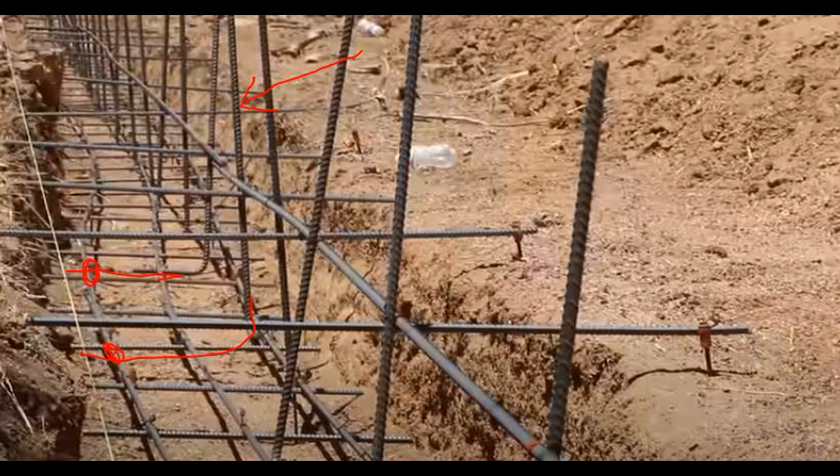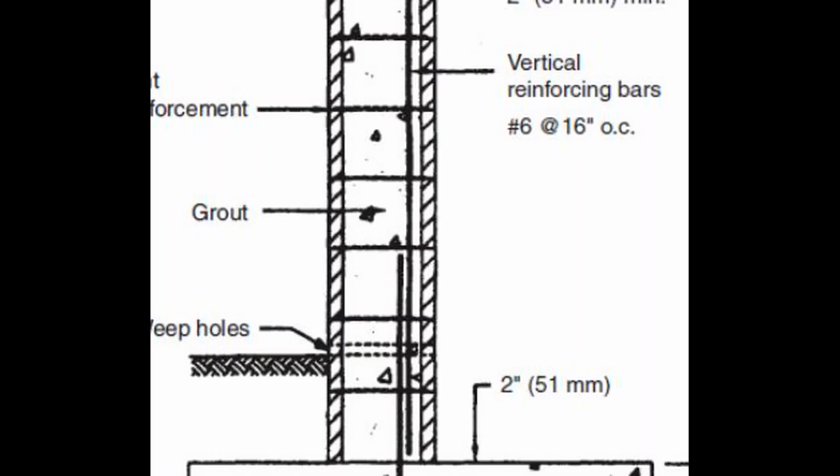So ideally, if they are subject to lateral pressure, which can be from soil, clay, or maybe lateral pressure from the material, as you can see in the photo, then they are required to be tied not at the beginning, however at the end, as you can see in the photos, where the weep holes are to be provided at the same location.